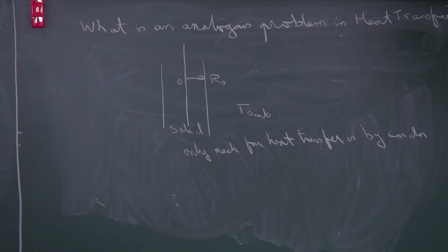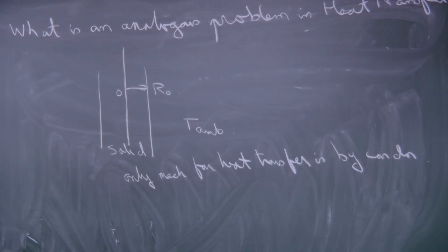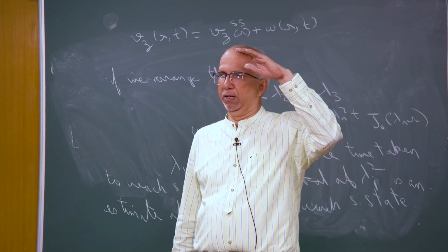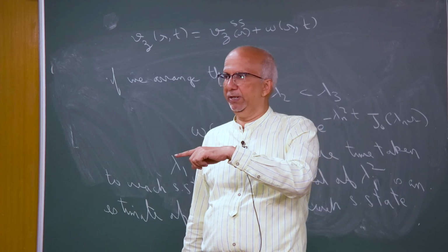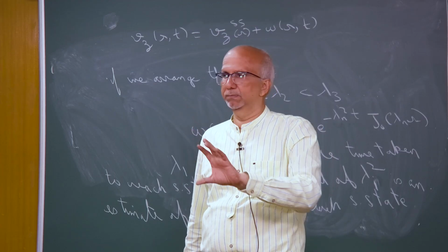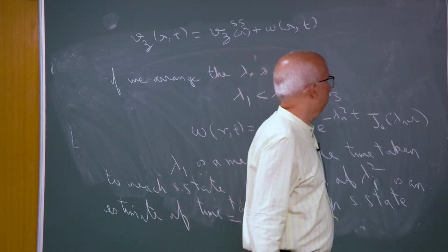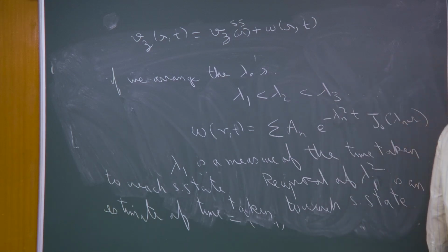In the earlier problem, when we did the fluid flow, the only mechanism of momentum transfer was by the viscous term. Okay, the viscous term, remember mu 1 by r d by dr, that is like a conduction term.